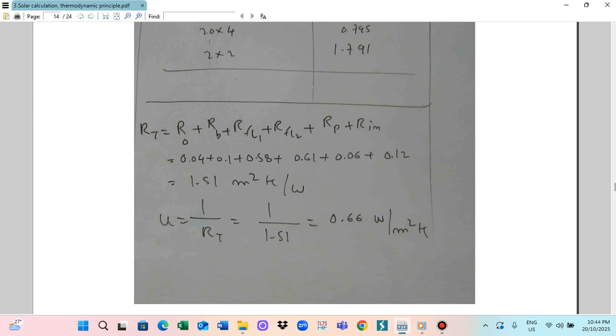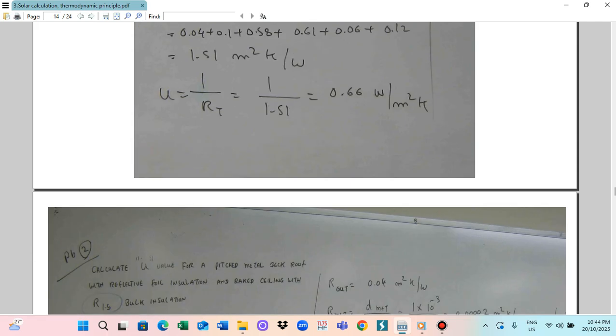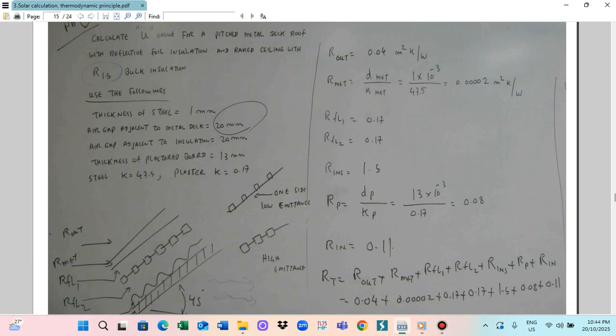So we have to find the U value. So we have to find the resistance of any bulk material. So there will be the plate, glass, wood, glass insulation we calculate, and then we will find the R equal to 1 by K. So this is the first step. So U means the overall heat transfer coefficient, U has to be calculated. So this is the way to calculate.